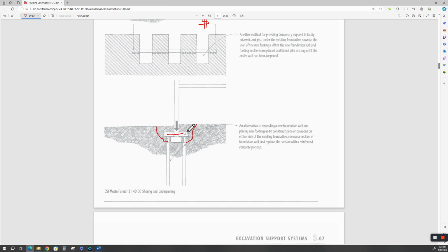Now, how are you going to drill this under an existing slab? Well, if this is big enough, you can bring in a small bobcat with a drill and start drilling this shaft. Okay. Again, that means you got to break this concrete out, drill down through here, then you got to get underneath all of this after you've removed it, form and cast this, and try to pin this new concrete to the existing wall. Very, very expensive. And then you got to repair all the work you did.